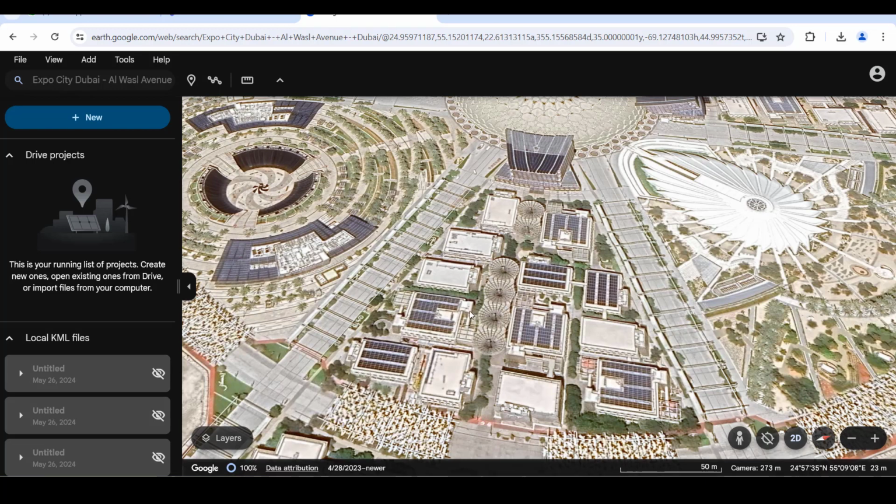That's why we need to publish or share the same coordinate system for all the linked files in a project. If you link any building in context with only those two buildings, you will get the correct location in that particular file, as well as in your main federated model. So both ways you will get the correct location and orientation.